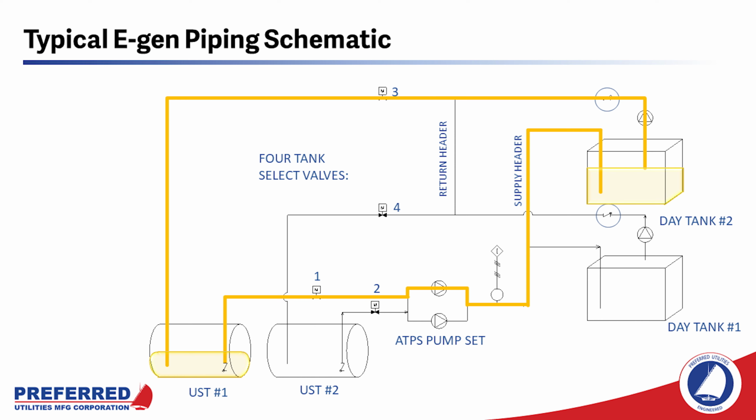Now, the discharge side is totally different. There, the pumps are pushing the oil, and we have plenty of pressure there because the preferred standard pumps are either 50 psi discharge or 100 psi discharge, which is actually quite a lot. And if we're doing a high-rise building, we can go to rotary screw pumps that can give us up to 300 psi of pressure. So there's just a lot more pressure available to us on the discharge side of the system than the suction side. And that's why we take such a hard look at the suction side.